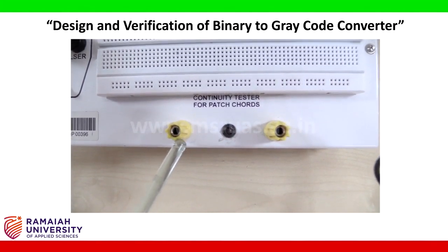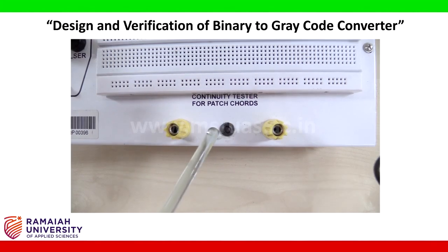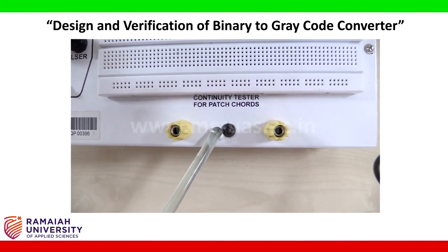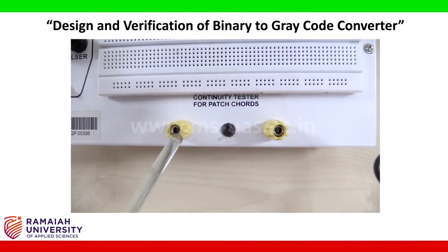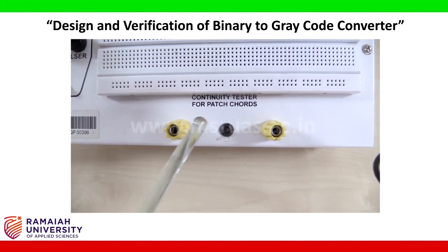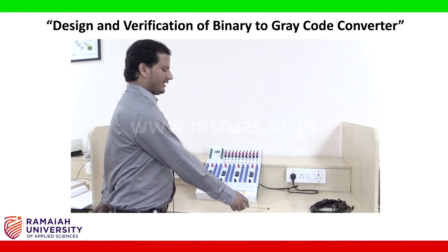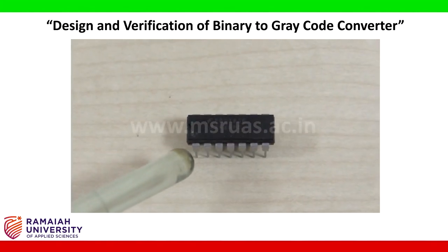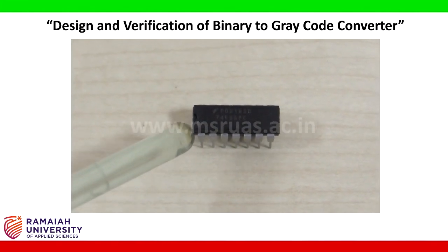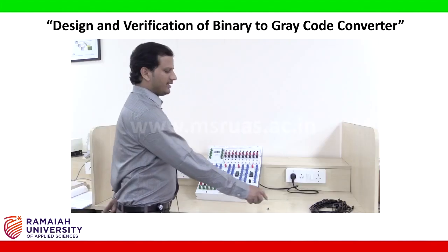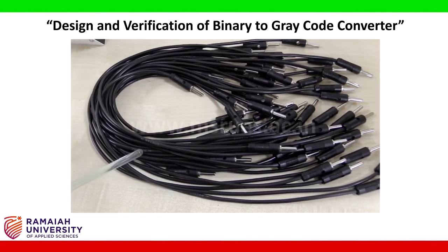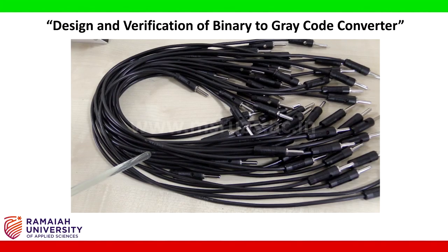If you connect the patch cord here and the LED bulb is on and the beep noise is coming, that means the patch cord is working properly, otherwise the patch cord has some problem. 7486 IC. This is the IC we are using in this experiment. This is the XOR gate 7486 and patch cords. These are the patch cords we are using to connect the logic diagram.